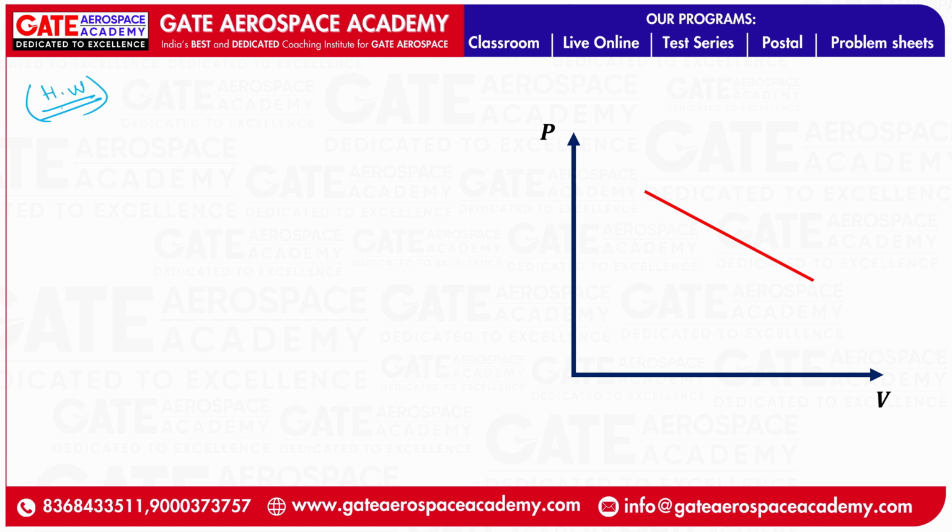What will be the final answer for this? That will be the area under this curve. This will be the area. And obviously this area is the summation of the area of this triangle plus the area of this rectangle. This will be the final answer. So you can derive the expression for work done for this kind of process where pressure varies linearly with respect to the volume.